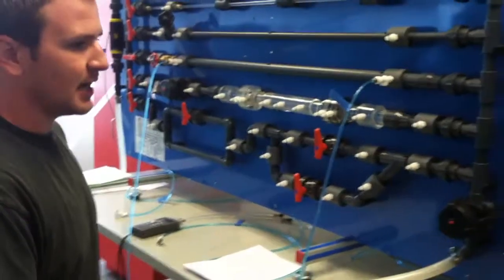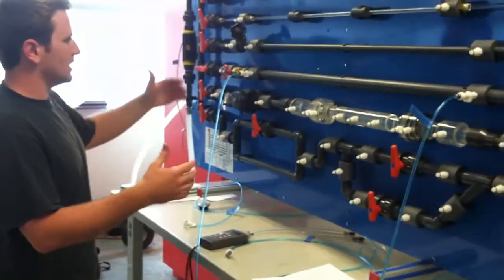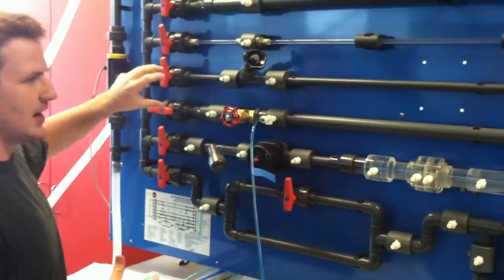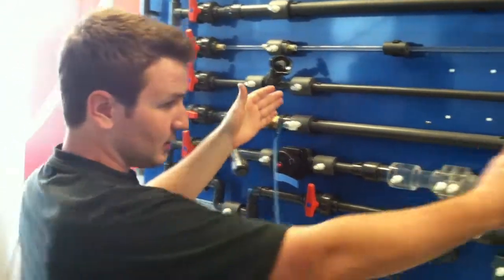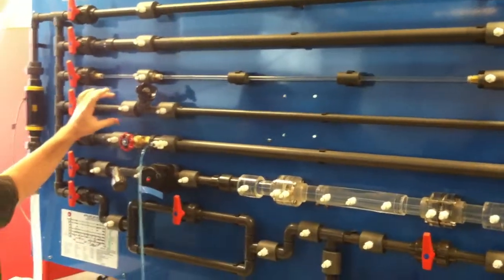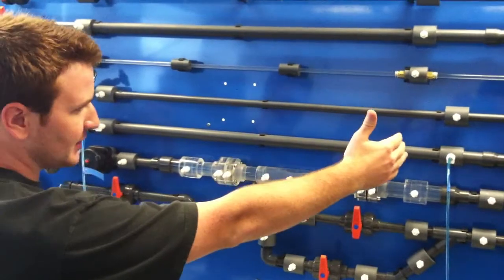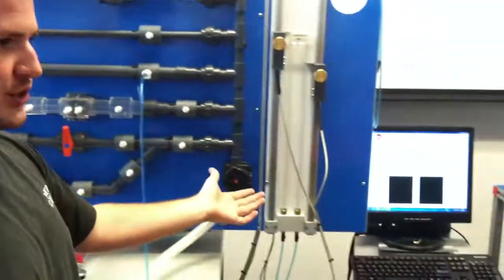And we'll do that, we'll throttle the flow rate 5 times and get 5 readings. And then afterwards, all we do is we switch on this valve to allow the flow through here, through this pipe, and we get readings at point 1 and point 2. This pipe is a 16.5 millimeter pipe, and the length difference is also 1 meter. And then you just do the same thing.